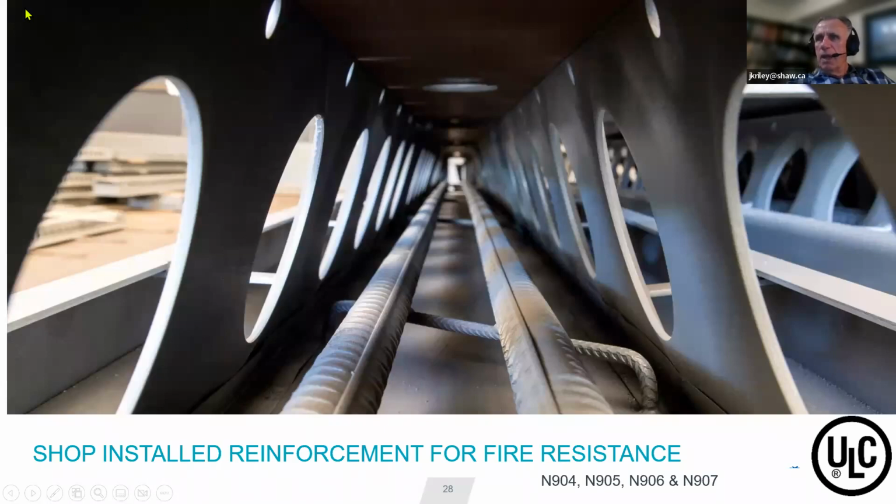So what you see here, you have a hierarchy of connections between the beam and the deck, regardless of whether it's mass wood, long span metal, or hollow core. Okay, so here you can see these holes are for the transverse rebar that I showed you earlier on. And these holes here are completely filled with concrete, and the concrete surrounds the fire rebar. And you can see here we have a downturn buildup. So this whole area is completely filled with concrete. And as you well know, concrete becomes a tremendous heat sink. So the heat that's generated from the fire below is absorbed in this assembly and vented out through the top here. And that structure can survive for up to 4 hours.